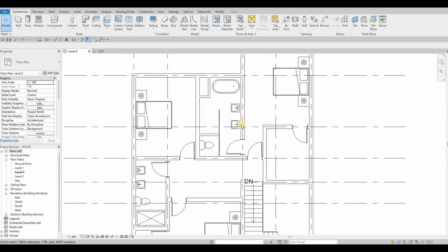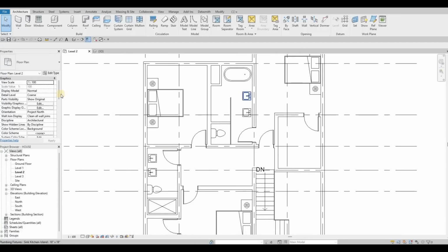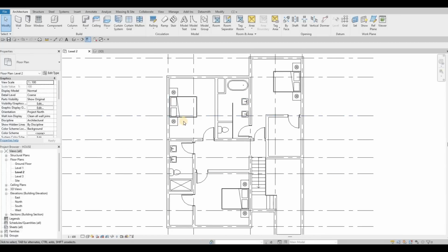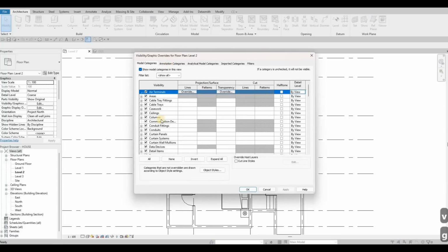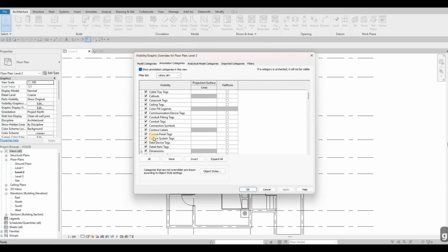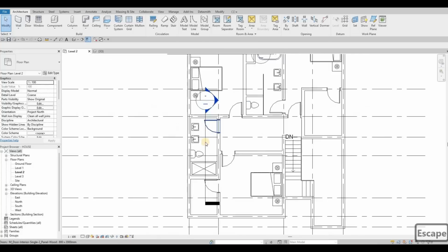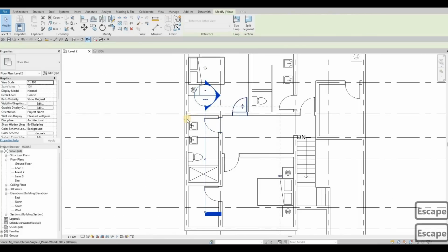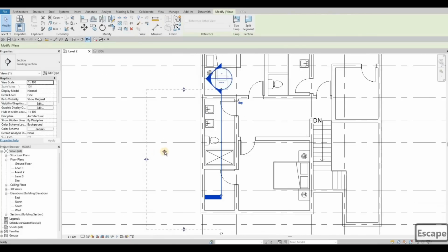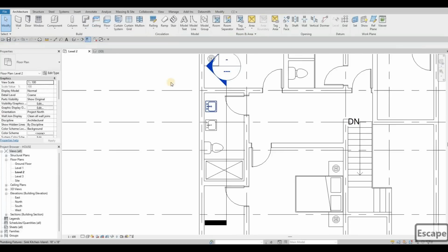Next thing is I want to add on all of this. I want to show the section right now, so VG for that, and then go to annotation, and then we did uncheck the section. That's why it's not showing anymore. So click on S so that you go to the S columns now, and then here I'm going to flip this and check how this one looks.